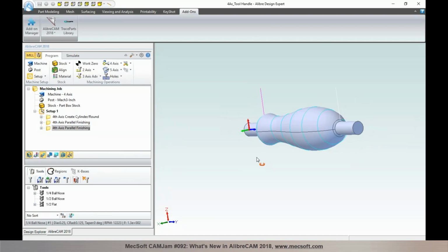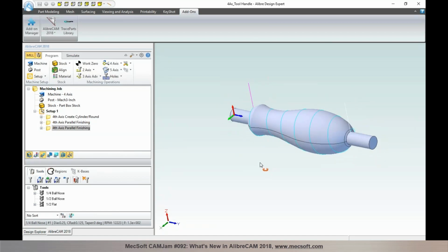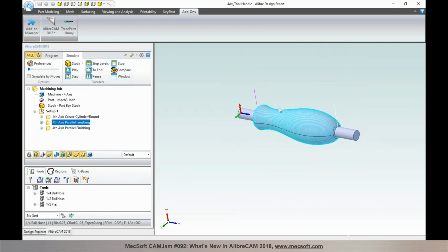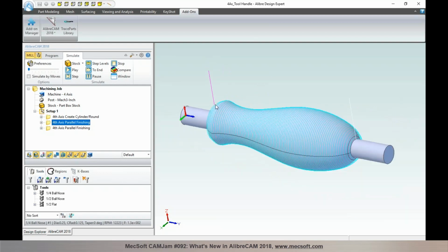So I'm previewing the toolpath on top of this model in here. Let me just run a quick animation so you can see the toolpath motion. This is basically a helical cut pattern, a very nice way to program a wide range of parts. And I've applied the same helical cut pattern with a much tighter step over on this example in here.